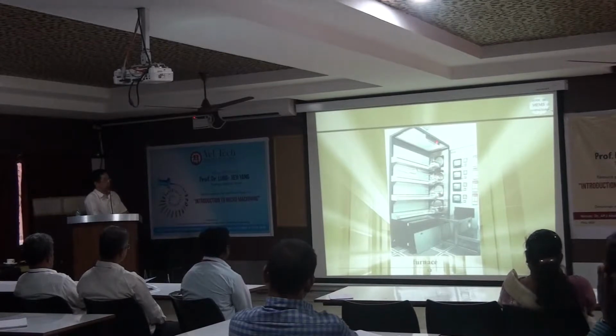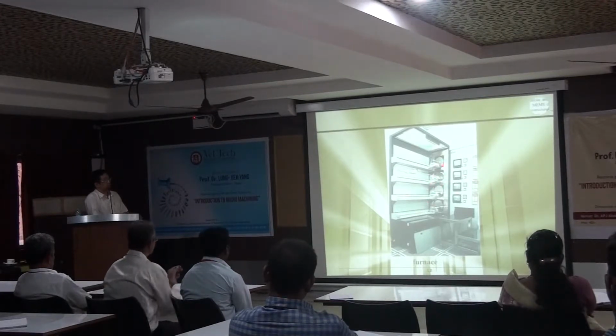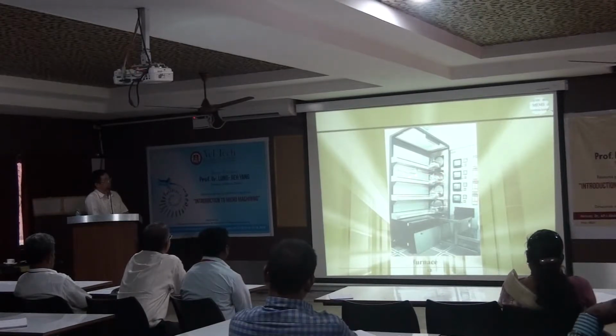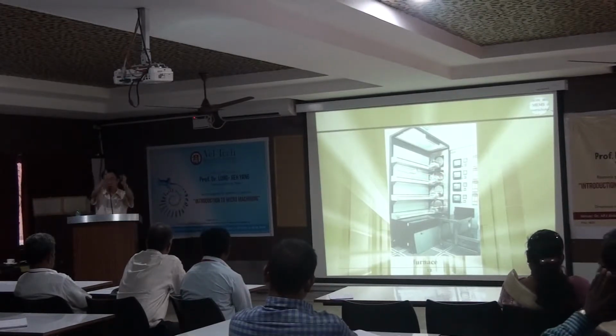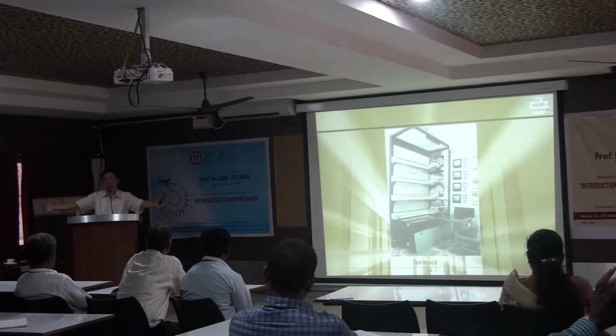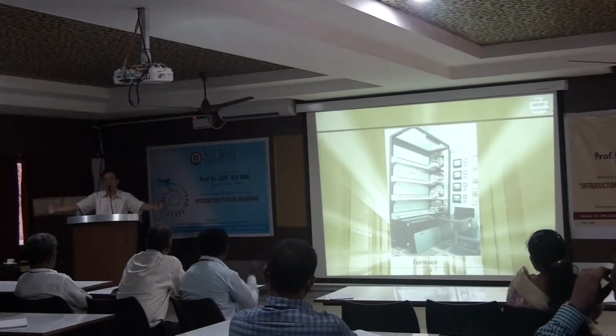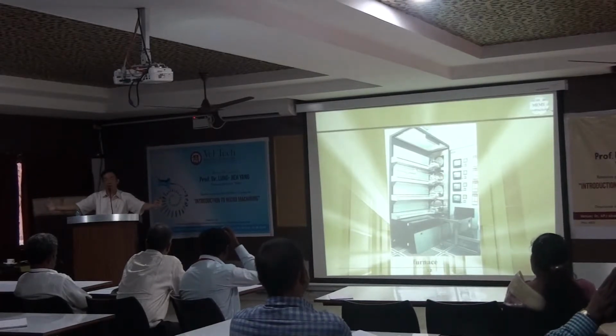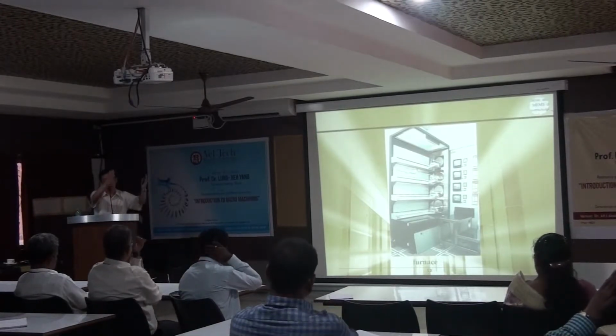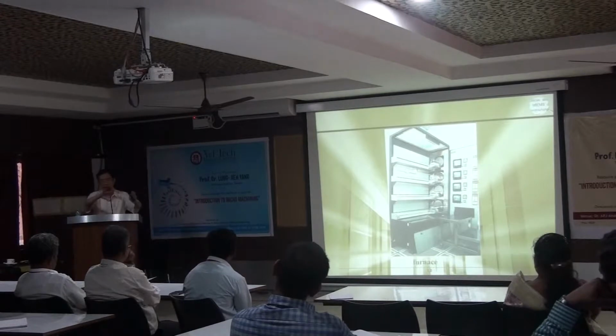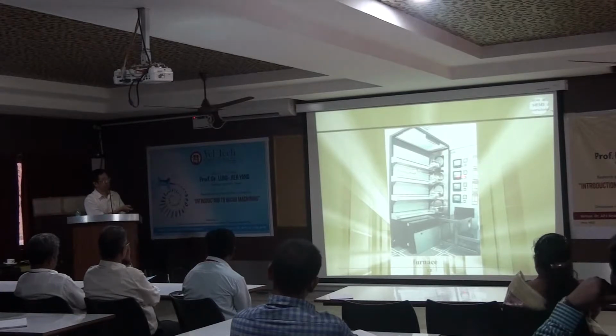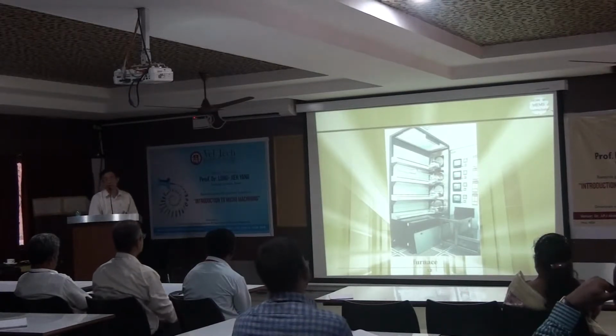This is the furnace, the high temperature furnace. It is a very old machine. It's a horizontal type. You can see all our wafers are vertical. We have vertical installation on the boat, the quartz boat. Quartz is crystallized silicon dioxide. The quartz boat holds the wafers vertically and then they are sent into the high temperature furnace gradually. And the temperature inside is more than 1,000 degrees C.